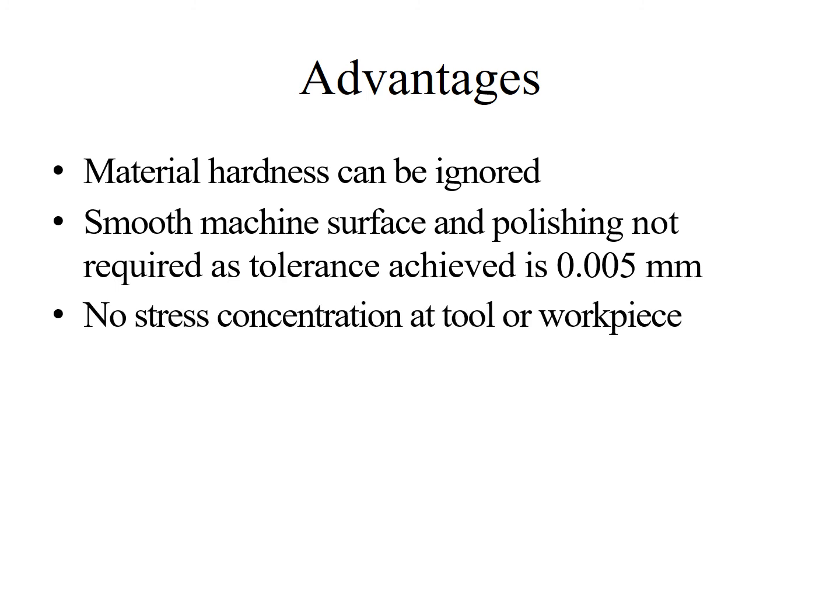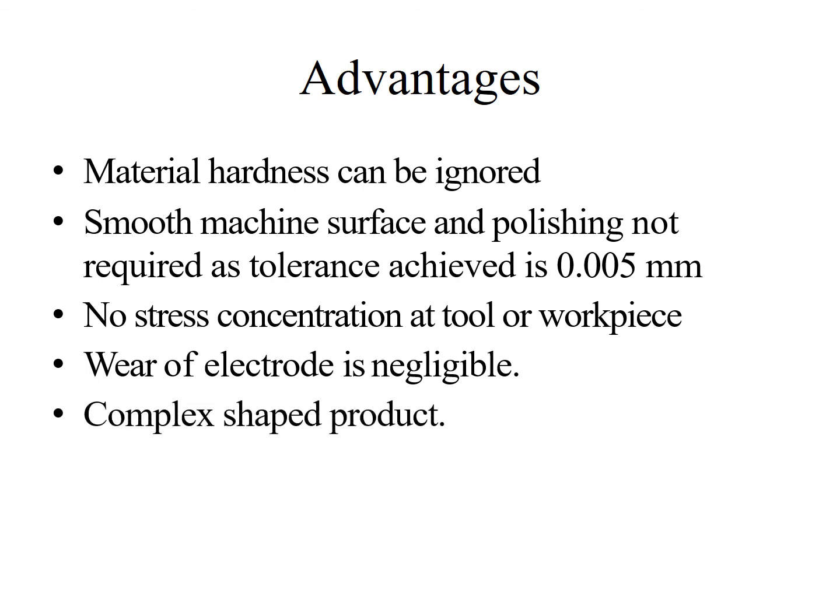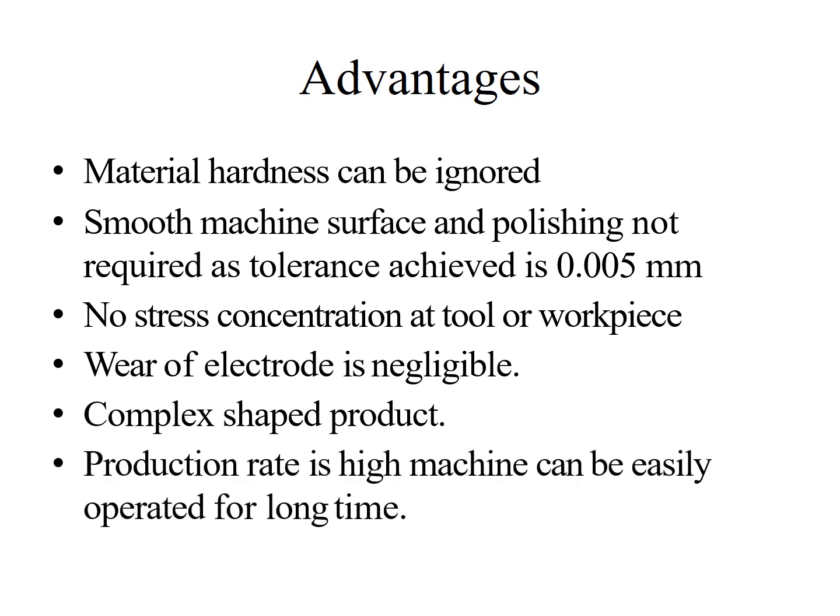There is no stress concentration at the tool and workpiece as there is no direct contact between tool and workpiece in this process. The wear of the electrode is negligible and complex shapes can be easily produced using EDM. Production rate is high and the machine can be easily operated for a longer time. Just filtering and pumping of the dielectric fluid is needed.